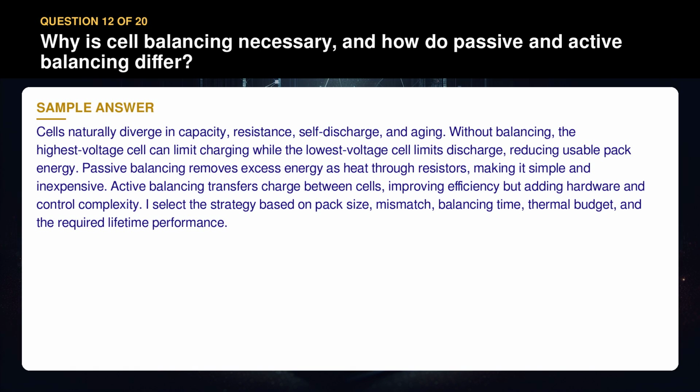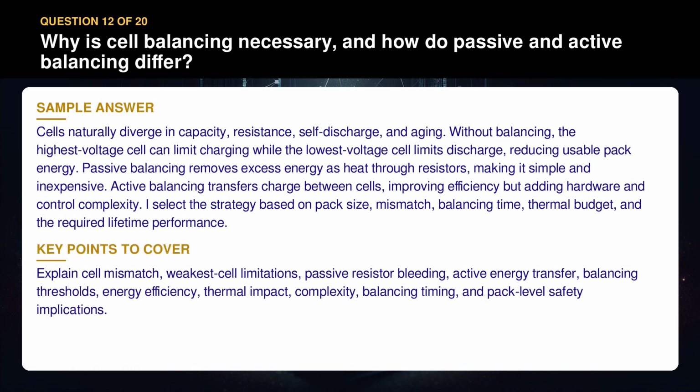I select the strategy based on pack size, mismatch, balancing time, thermal budget, and the required lifetime performance. Explain cell mismatch, weakest cell limitations, passive resistor bleeding, active energy transfer, balancing thresholds, energy efficiency, thermal impact, complexity, balancing timing, and pack level safety implications.